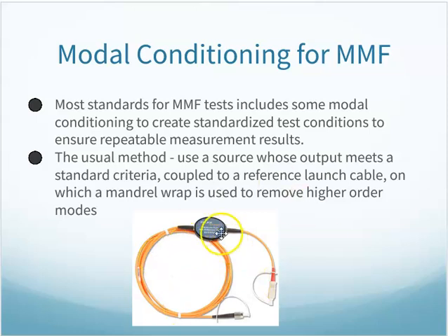So we're going to use this right here as our reference cable, and in there the fiber goes around and actually does that filtering, removing those modes that are bouncing around the fiber, not the ones that are going straight down through the middle of the fiber, if you will.